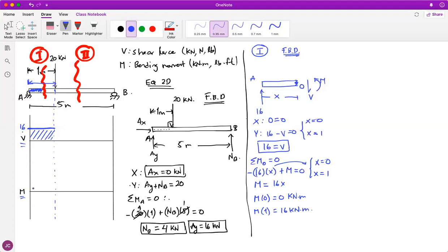So what you are looking at here is that it's actually ramping up. This bending moment starts at 0, okay? And then it starts increasing. The value starts increasing till you hit 16 kilonewton meter. It's different from this 16. Okay, it's not this 16. This 16 has units of kilonewton. These units are kilonewton meter. These guys are of different nature. Okay, well, okay. So you have the bending moment that is going to increase from 0 till 16, and the highest value for this part of the section 1 is actually 16 kilonewton meter when you hit 1 meter. Okay, that's what the information is telling you.